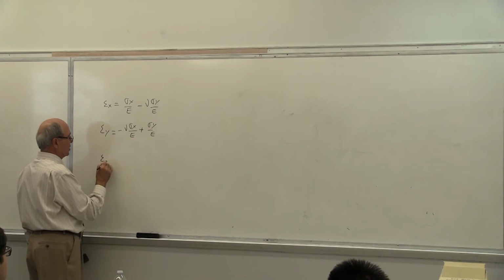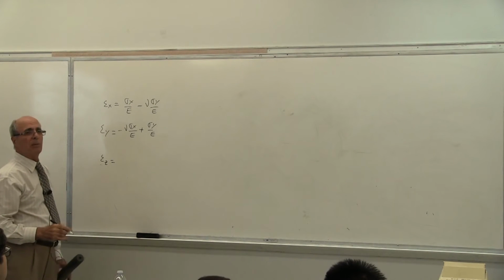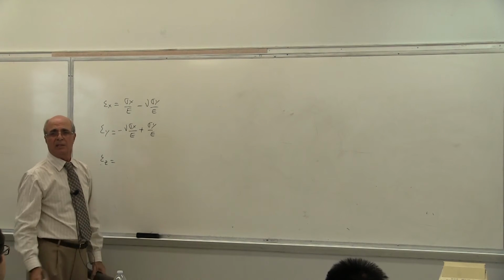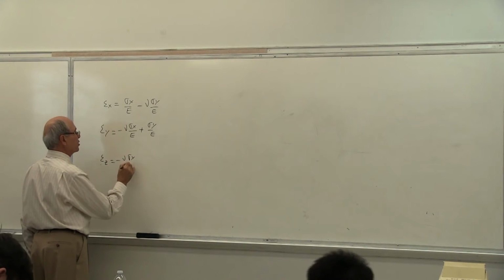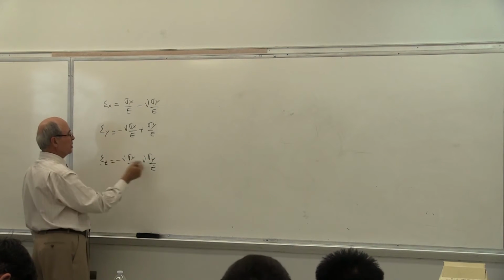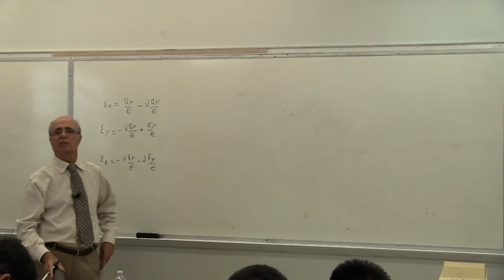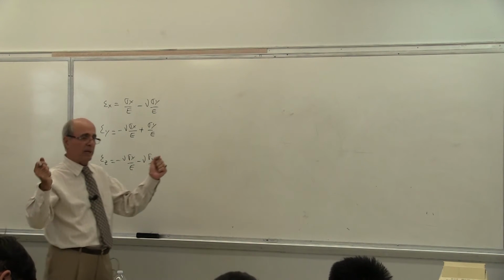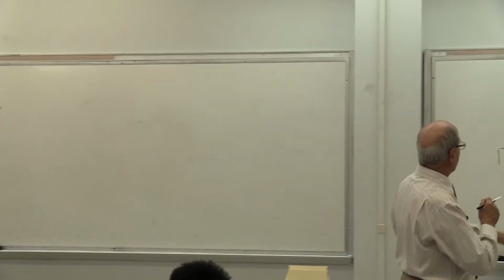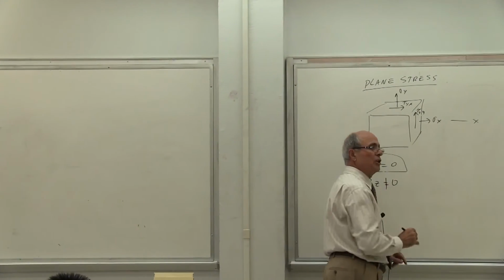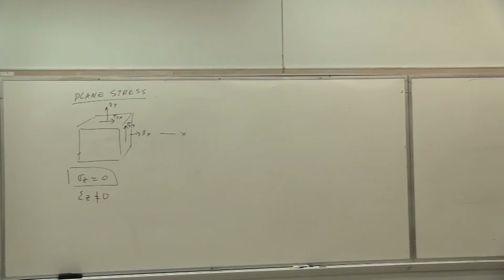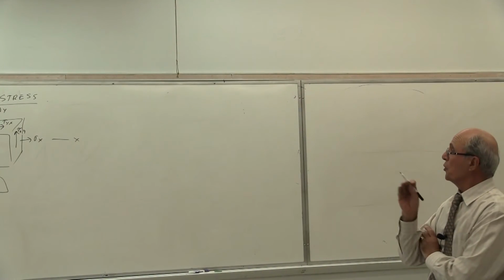Now, the question you want to answer is this. Calculate principal strains, which is two of them, maximum and minimum. Is that correct or not? Yes, exactly like a stress. Then find the absolute maximum shear strain. Notice we have one circle, then we turn it into three circles, in plane and out of plane. We have gone through that as well. Is that correct or not?